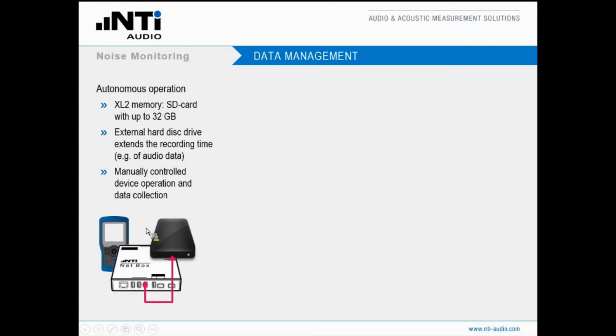Keep in mind, the setup of your noise monitor, of this whole system here, and also the data collection have to be done manually. So when you want to get the data that have been recorded, you have to walk to that location and you have to copy the data from the hard disk to your PC.